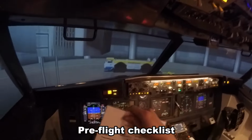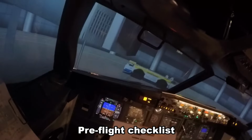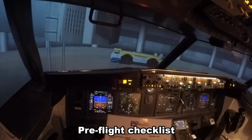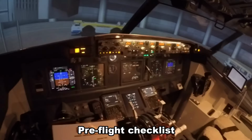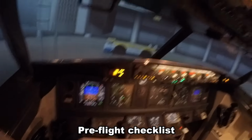Alright, so that is complete. We'll just do our pre-flight checklist. So navigation, transfer and display switches, normal auto, window heat is on, pressurization mode selector is auto, flight instruments heading 072, altimeters 1009, parking brake set, engine start levers cut off, pre-flight checklist is complete.